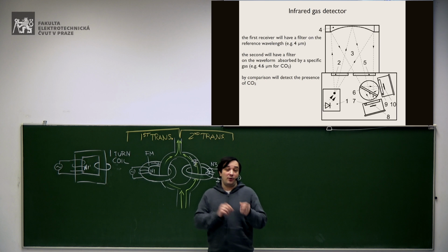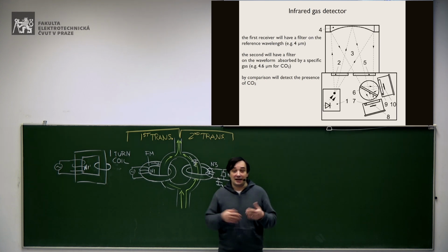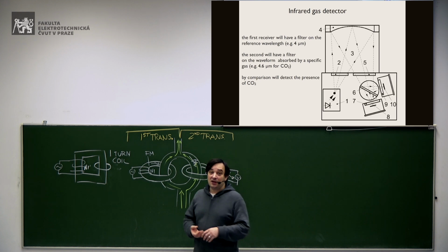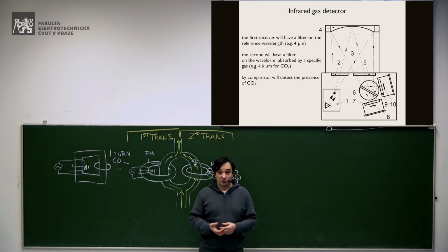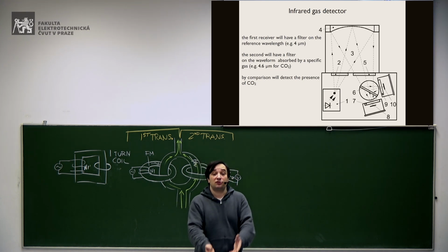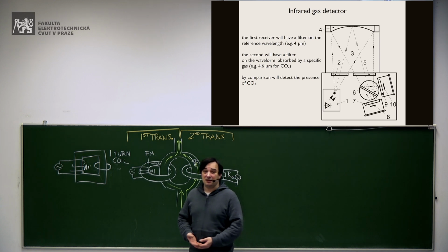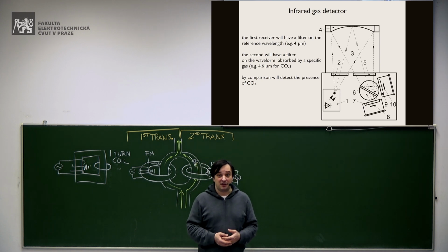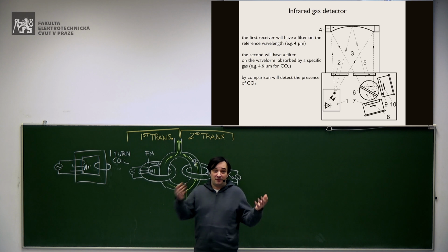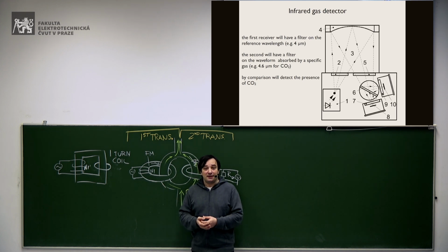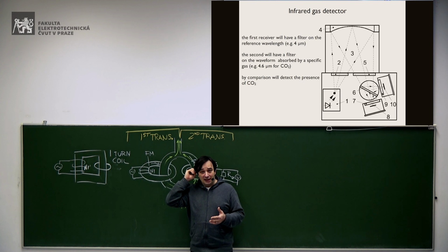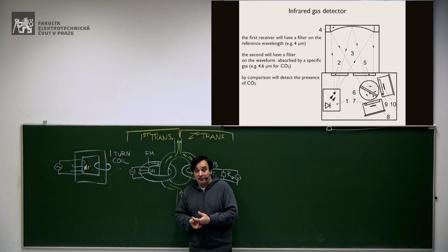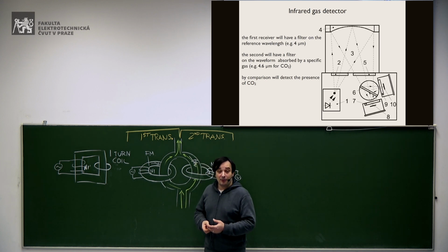As usual, we always use a comparison with another element, with another physical quantity, which is not affected by what we want to measure. Because as a matter of fact, this variation could be due, for instance, to the source of radiation changing. So maybe this source of radiation is not very stable. Maybe it just drops for God knows what reason. So you have this light which decreases. You think it's due to the presence of the carbon monoxide inside the chamber, but in fact, no.